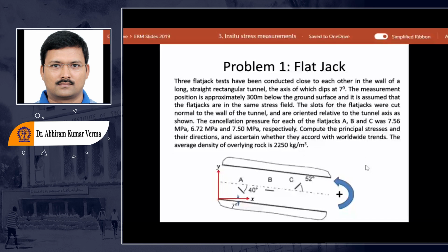At any point below the surface of the earth, we can define the stress at a point, and the stress is maybe the stresses in a principal plane. Definitely we'll get the three values of principal plane stresses. But if I'm measuring out of the principal plane, then at that point we will get some shear stresses also. So we have to have a measurement of all these things.